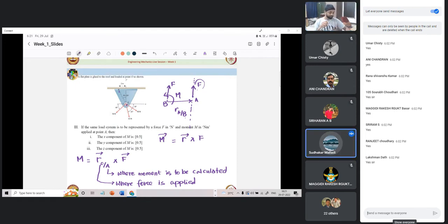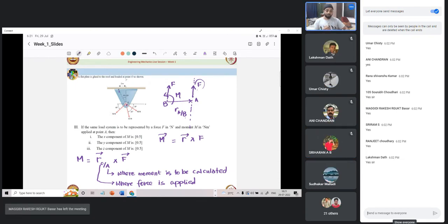What about the F which was placed at B, pointing upwards? That is still there. It is not left out. Only the bottom force that was applied creates a couple. So if there is a point where you have applied F and you want to translate it to another point, that same force goes, and in addition to that force, a couple also exists. Okay, fine. Thank you.